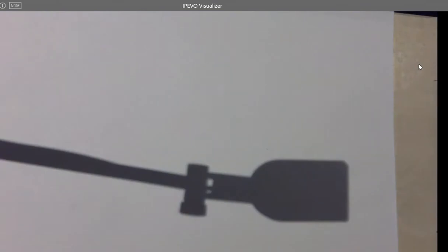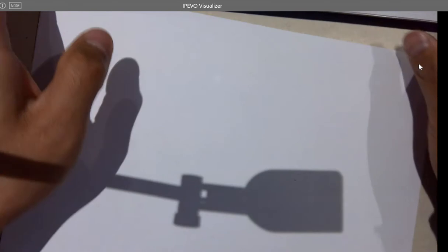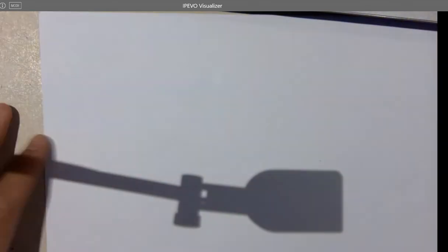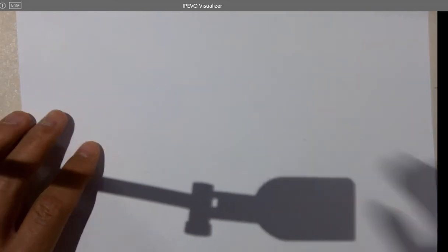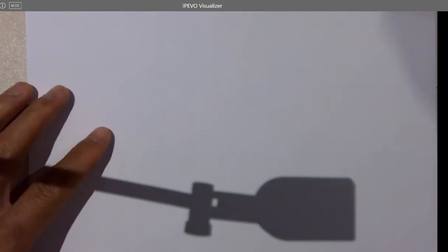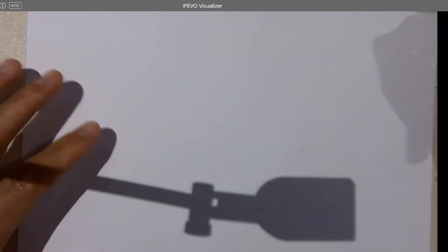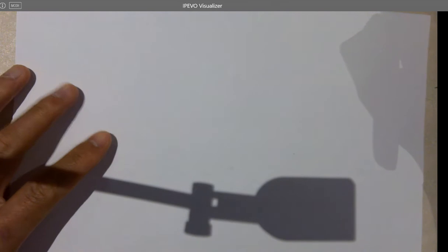So we are going to work on high-speed adders this time because one of the labs in the following weeks will be an adder design. But an adder is simple. We have learned it in digital logic, right? It's fairly simple combinational logic. But if you are asked to design a high-speed adder, it has to be AOI logic designed in complex CMOS circuits. So we have to revisit the structure of the adder.